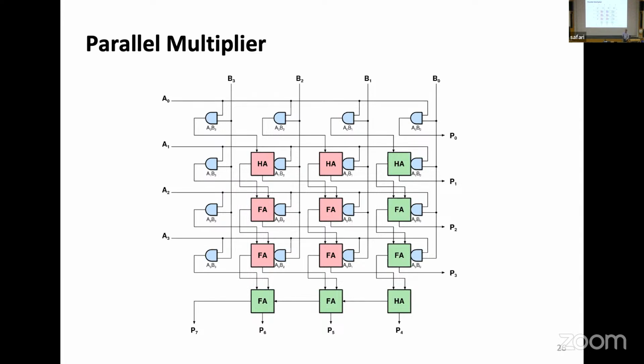So the question is, how for 4 bits, 5 bits, 6 bits, 7 bits, 13, 17, 113 bits in a processor, you don't know what the users want. Maybe they want to add this or that and multiply this and that. Do I have different multipliers? Usually you end up having one big multiplier that can be configured to do, for example, a big 64-bit multiplier that can do 2 32-bit multiplications or 4 16-bit multiplications.